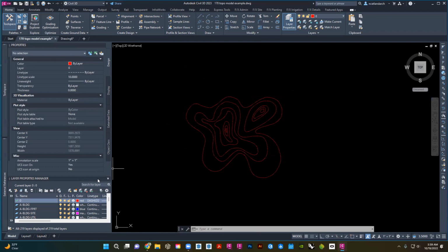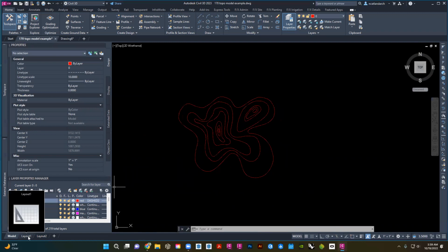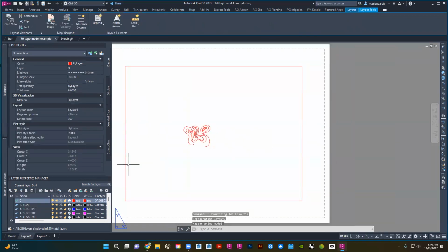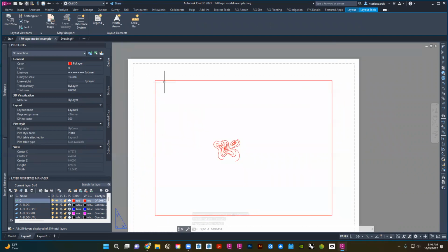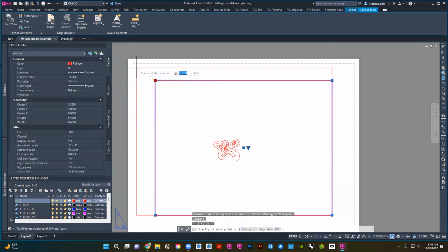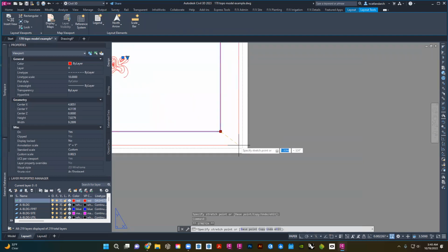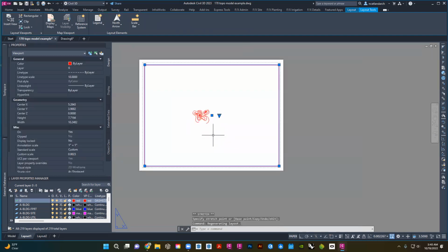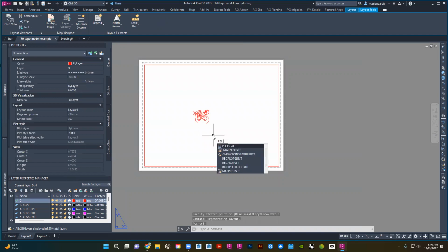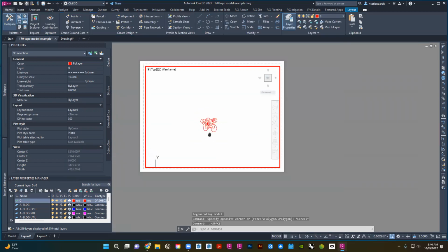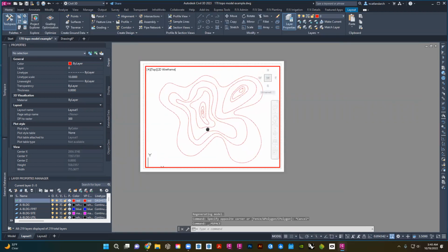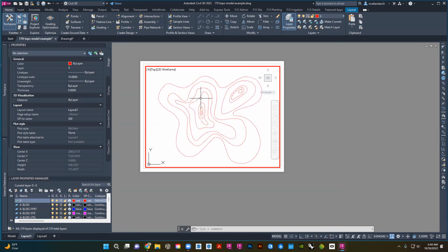Once you have this, have you all go to your layout. I just want to know that you know how to do this. I'm going to type in paper space line type scale and make it 0. And refresh, and it shows what's on the screen. Double click here, and just eyeball it. Don't set any specific zoom, just kind of fill the screen.